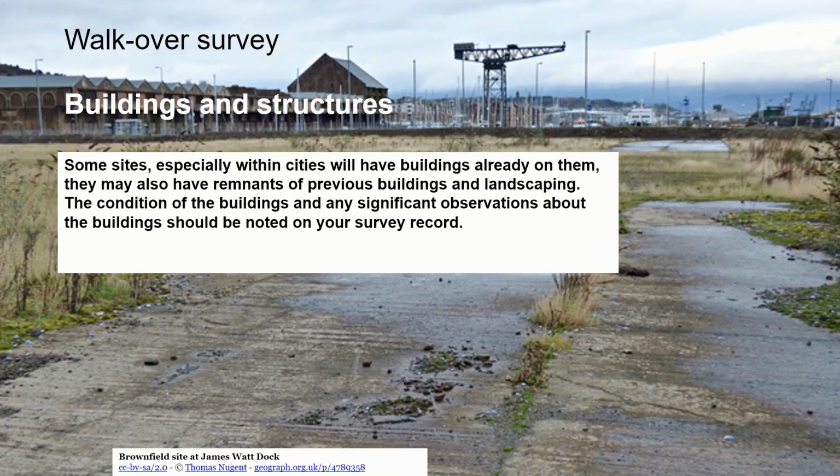If you have buildings on your site or next to your site, they can give you some valuable information about the condition of the ground. If there are buildings on the site and they show evidence of cracking or movement, then that will maybe tell you about how the ground underneath your feet is formed, what the subsoil may be, or what the bedrock may be.